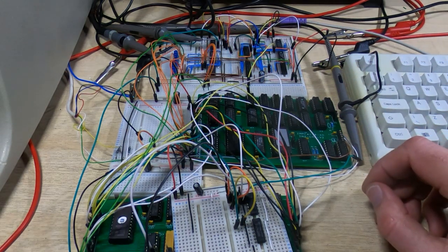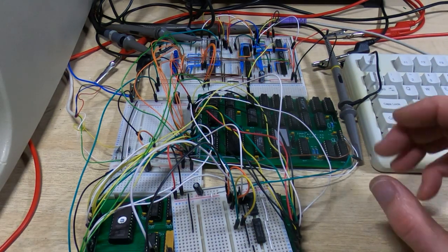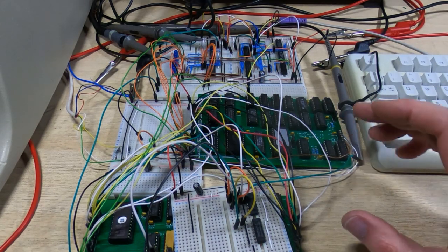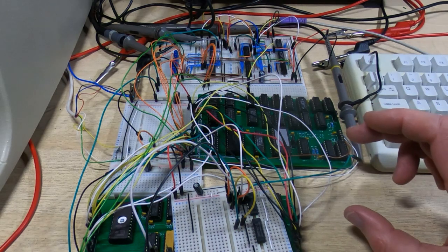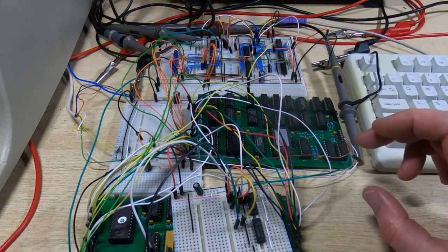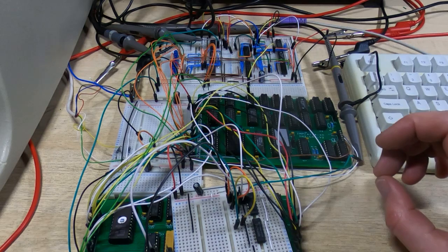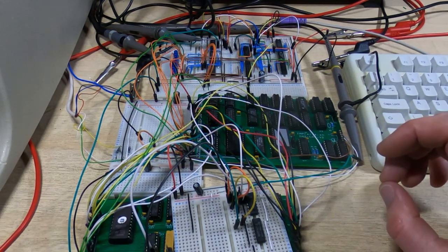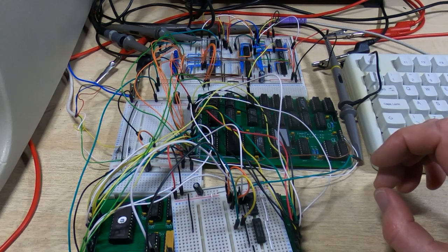and there's a character there, let's say there's an uppercase G in that location, then we need to read that character first, set the cursor bit, and then write the character back to that location in SRAM. If we can't read it, we don't know what character's there, and we'd end up overwriting whatever data's already on the screen.